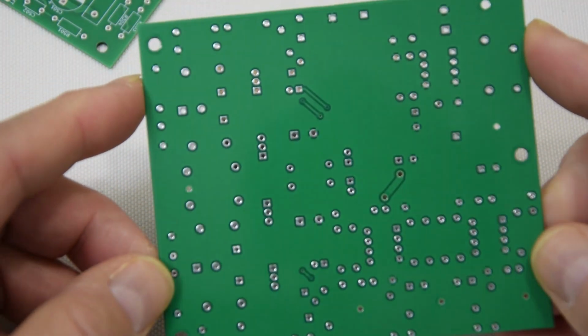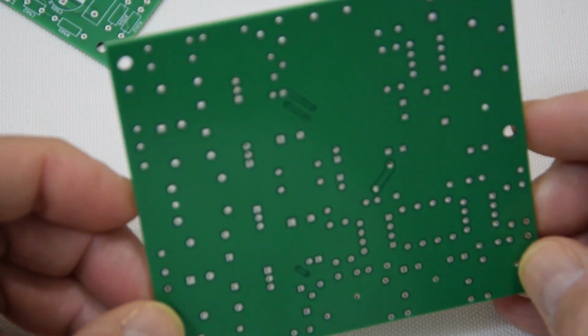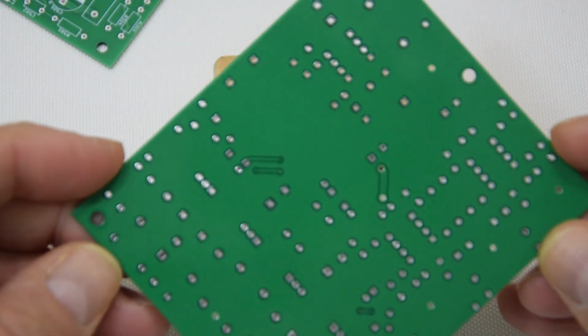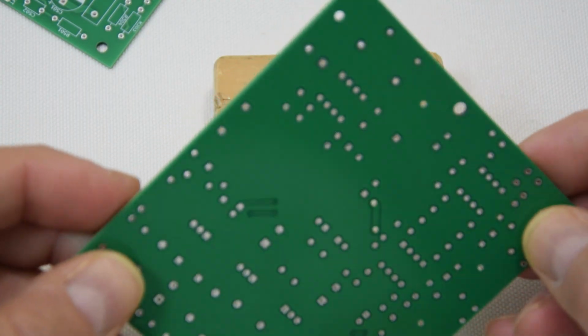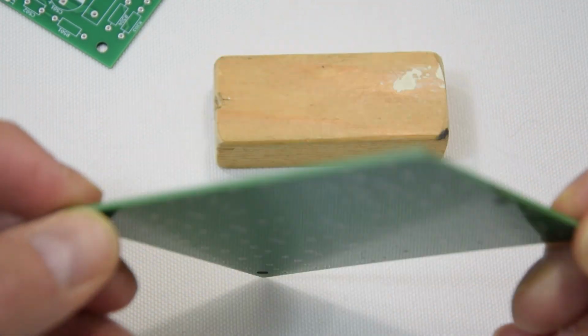That's this side of the PCB. It's the most effective way to ensure solid grounding and minimize distortion in the return path. I only had to route a couple of crossing traces through it, so that's okay. So I'm very happy with that.